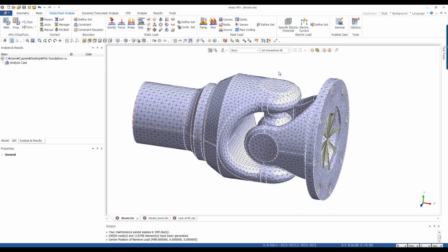But another way of understanding the contacts is to think about them as an additional form of constraints. Actually, the contact is not the constraint, but it creates a relationship between the contacting pairs, and because of that we can create some behavior between them, like the faces of the parts can move relatively to themselves, they can be welded, they can be fixed.